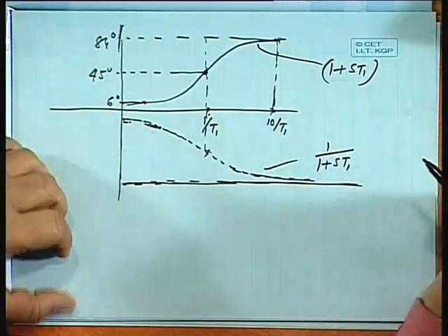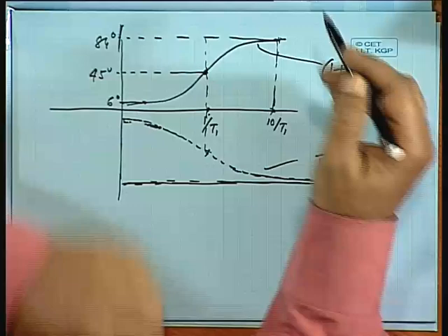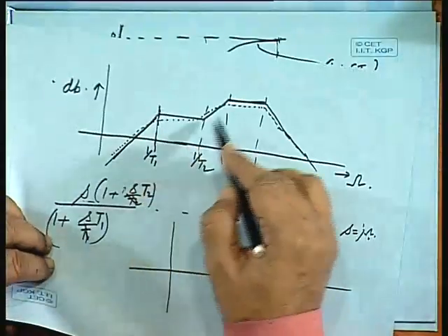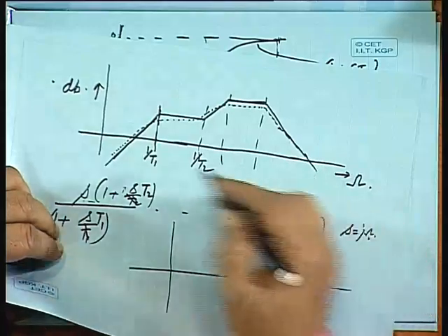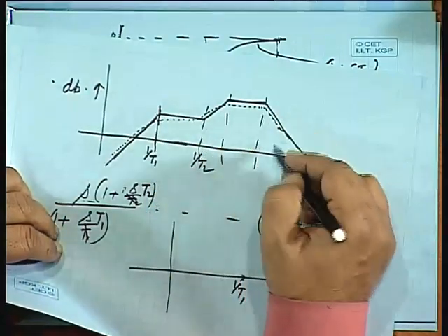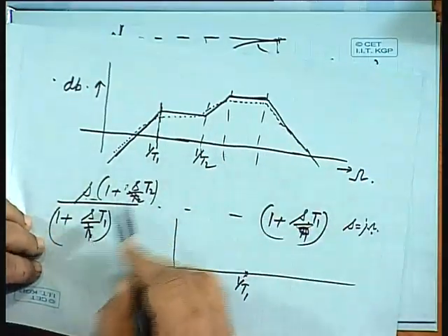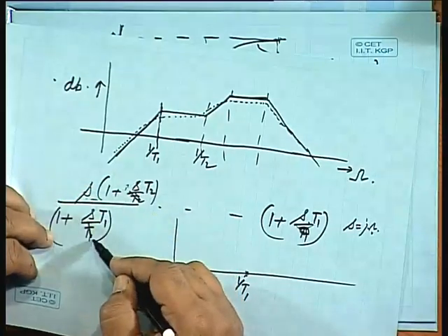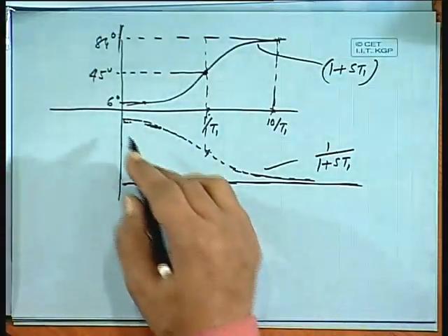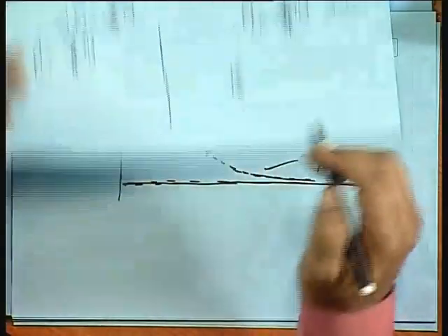in the numerator. So, once you are given a gain function, you can resolve it into approximate asymptotes and then find out the frequencies and hence their nature, whether they will be appearing in the numerator or in the denominator, and accordingly you can construct the contribution of phase for each component.